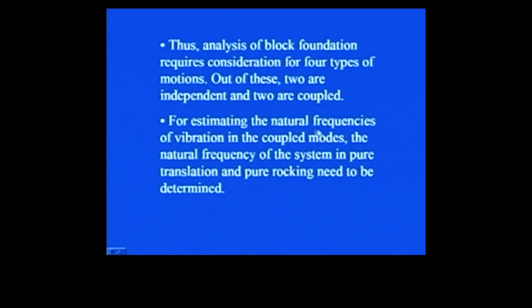For estimating the natural frequencies of vibration in the coupled mode, the natural frequency of the system in pure translation and pure rocking needs to be determined. When we are talking of rotation about the x or y direction, either pitching or rocking will come into the picture. Since they are coupled motions, first we need to know what exactly the natural frequency is in pure translation and pure rocking condition. How we do that we will see in subsequent slides.